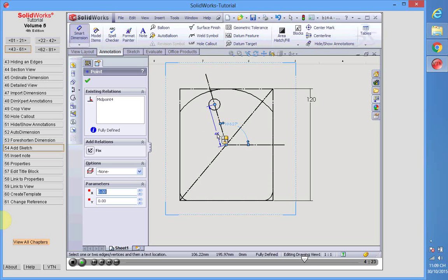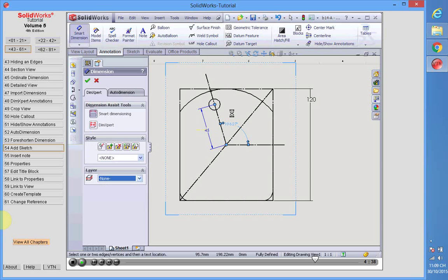When I find the point where I get the dimension I need, I right-click, and that locks the dimension. If I want to unlock the dimension, I can just right-click again and then adjust it as needed. You relock the dimensions with another right-click. Let's make it dimension-driven. OK.